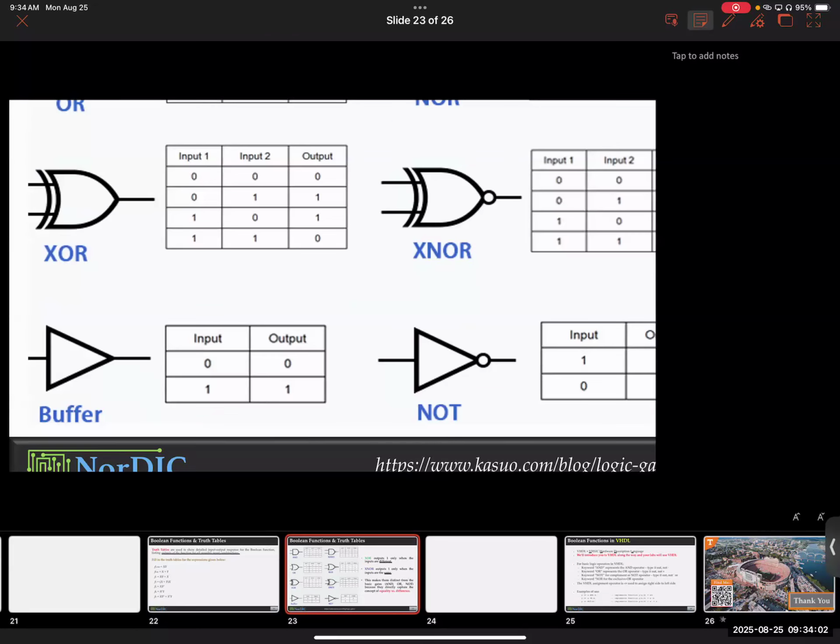So we could also use a real life concept. Notice you have 0 as output when both inputs match. So when both of them are 0 or both of them are 1, your output is 0. And when you have a mismatch between the two inputs, your output becomes 1. All right. So XOR, also known as exclusive OR, is a unique logic that tests whether two inputs match with each other.